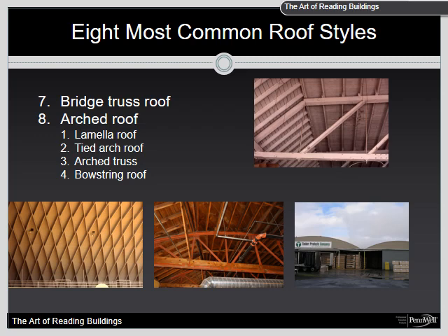Although the tied arch roof is similar in external appearance to bowstring roofs and possibly some lamella roofs, it is significantly different internally in that it uses horizontal metal tie rods and counters the lateral forces that the arch top beam places on the walls. Tie rods with turnbuckles are used below each arch member to help achieve the counterforce. The tie rods may pass through the exterior walls to outside plates, which can facilitate identification of this roof, or they can be attached to the ends of each arch where it meets the wall.